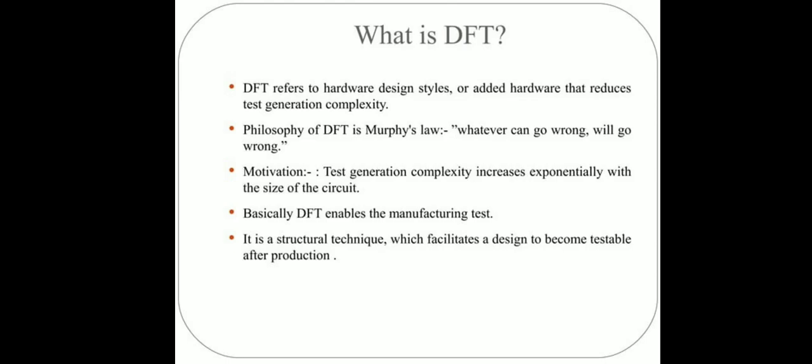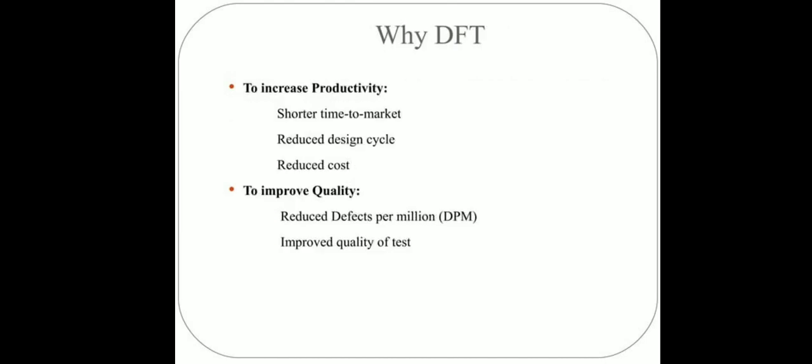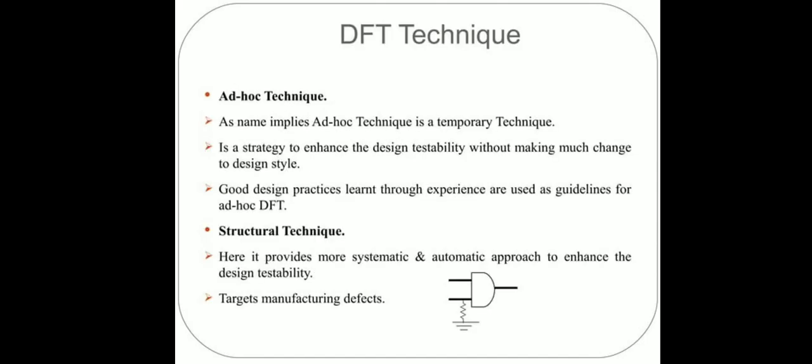So what is DFT? DFT refers to the hardware design styles or added hardware that reduces the test generation complexity. The motivation is that the generation complexity increases exponentially with the size of the circuit. Also, this enables the manufacturing test. It is a structural technique which facilitates the design to become testable after production. Why do we go for DFT? To increase the productivity and to improve the quality. In the case of productivity, there is shorter time, reduced design cycle, and reduced cost. In the case of quality, there are reduced defects per million and improved quality of test.